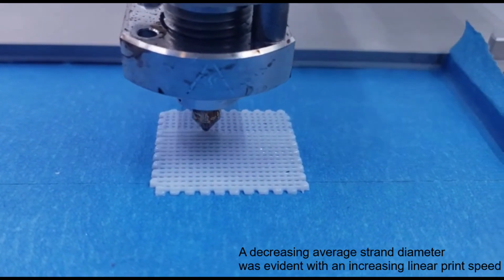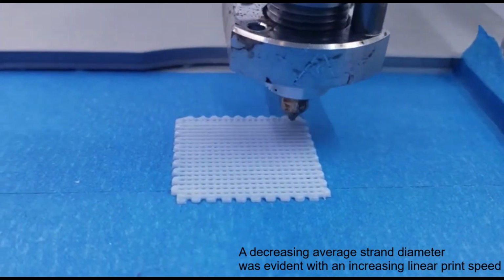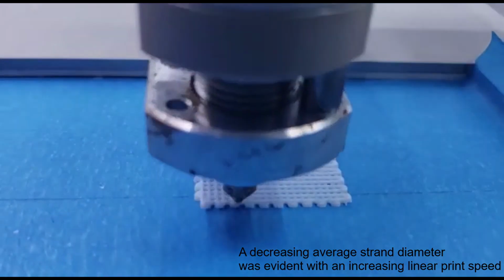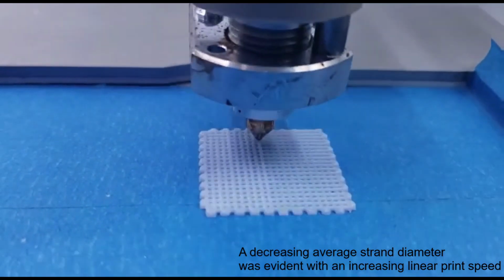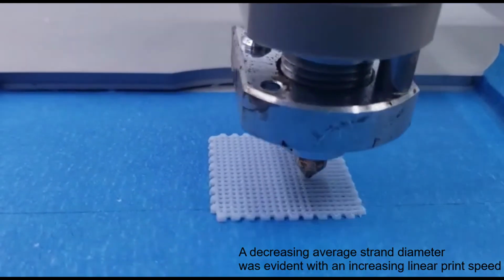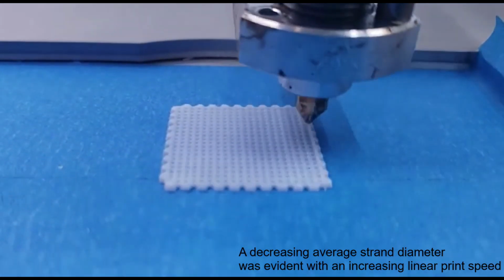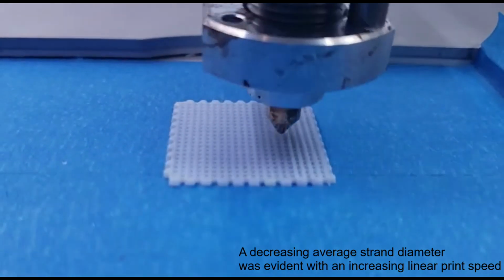Initial strand tests revealed that a decreasing average strand diameter was evident with an increasing linear print speed. This trend is related to the material extrusion rate when a defined pressure and temperature are applied. Strands with a larger diameter than the print nozzle experience a greater extrusion rate as compared to the linear print speed, resulting in excess material deposition.